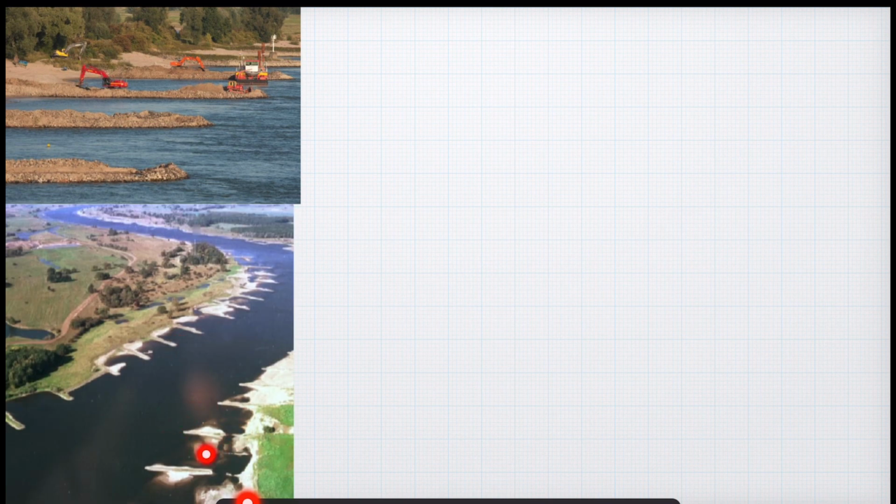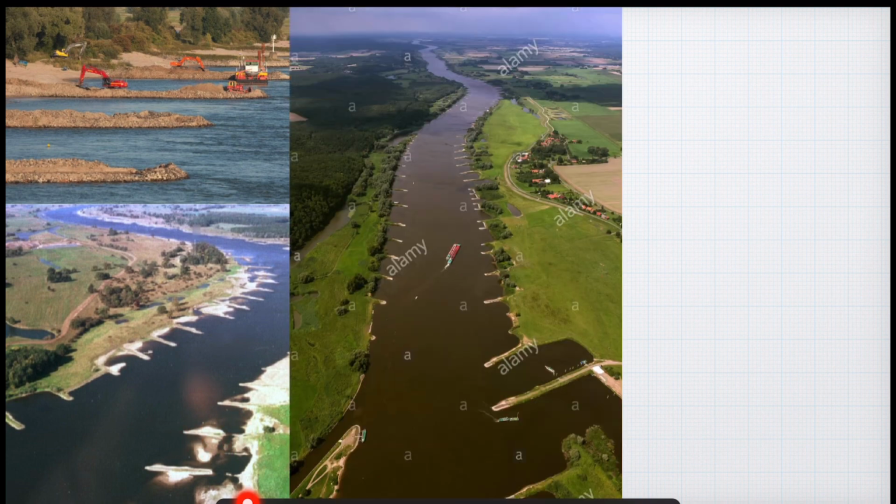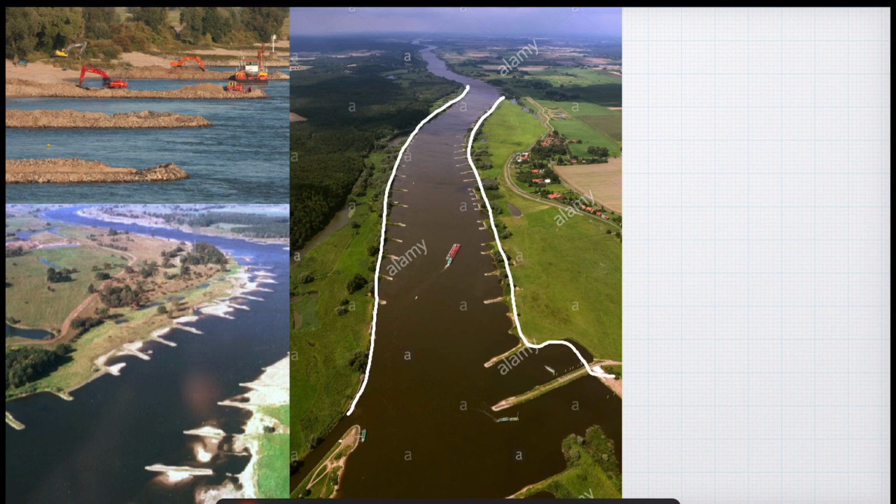So down the line, the groynes also get destroyed, so constant repairing of the groynes is needed. You can see in this image a good number of groynes being constructed so as to ensure the velocity of the water is reduced and the banks are preserved. Now you can appreciate that if we had gone for a marginal embankment throughout the length of the river, the cost of construction would have been very high.